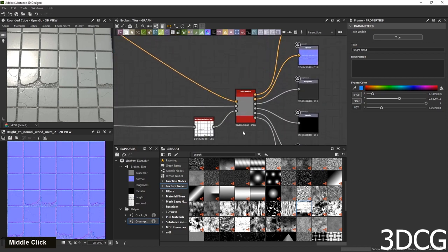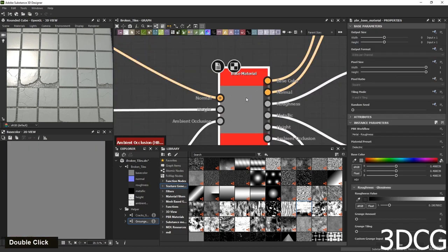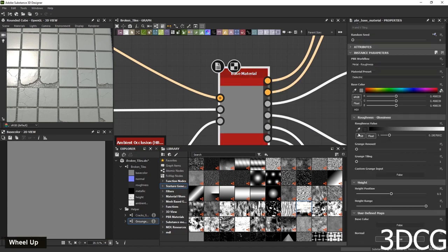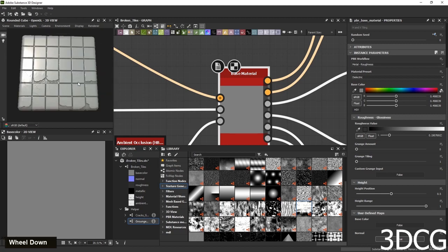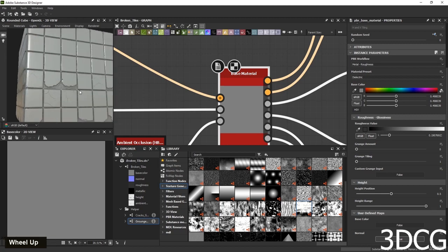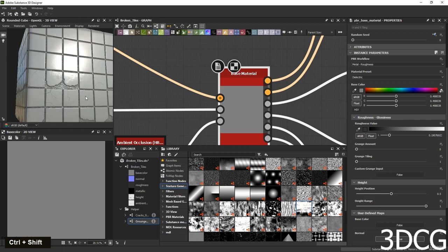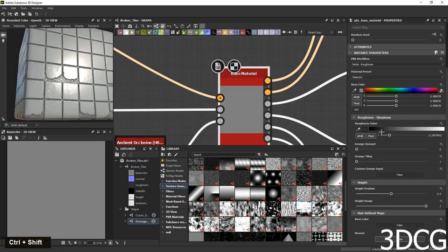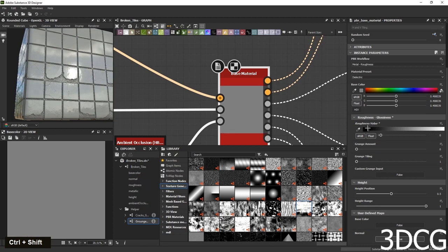If I want to demonstrate that, you can go to base material, and here inside the roughness glassiness area, a little bit zoom out, take the light. If I go towards black, it's going to be all glassy. And roughness and glassiness basically are the same map, but inverted.